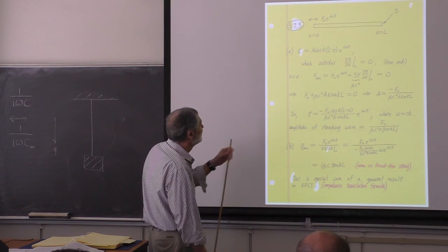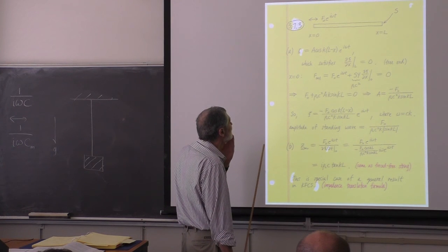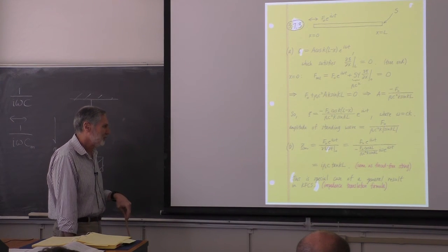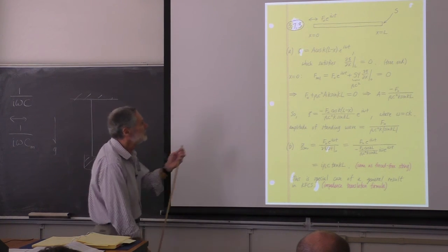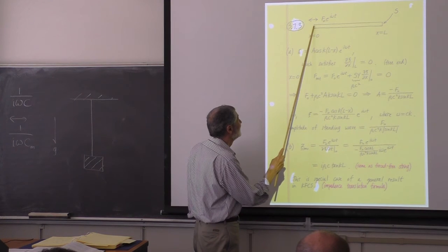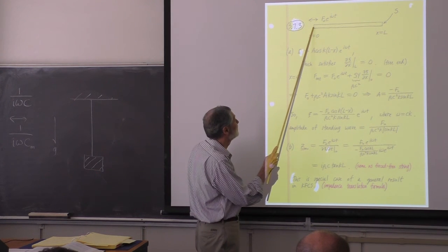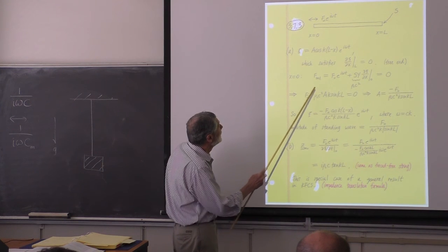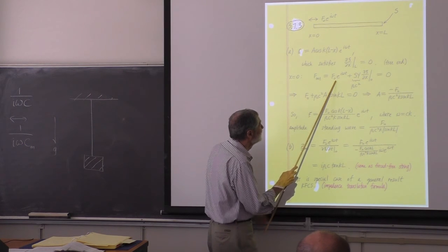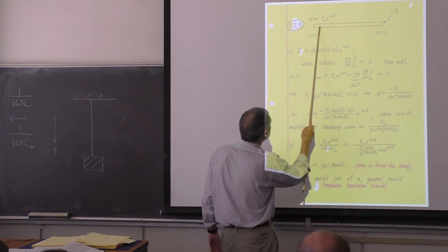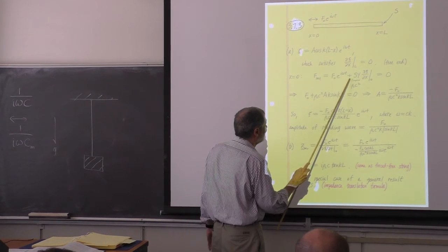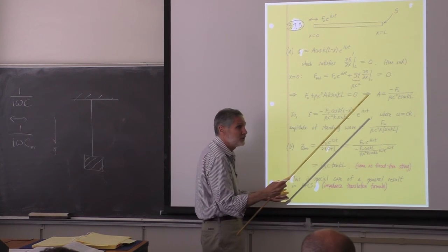So now I want to look at the origin. And here we could use impedance, but I think the point here is to derive the impedance. So as an exercise, we're going to look at Newton's second law. What does Newton's second law tell us about this end? There can be no net force on that, as we've discussed before. So here's that statement, the net force is 0. We have an instantaneous external force given by this. The force on the bar is, because we're going from right to left, we have to change the sign here. This happens in a string too.